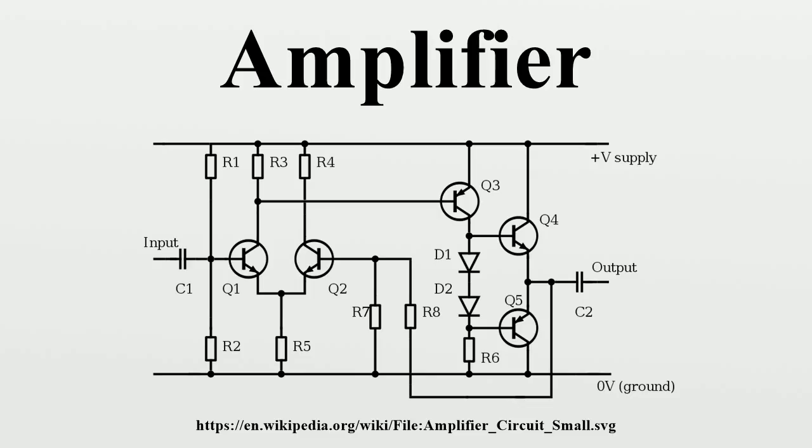Fully differential amplifiers. A fully differential amplifier is a solid-state integrated circuit amplifier that uses external feedback to control its transfer function or gain. It is similar to the operational amplifier, but also has differential output pins. These are usually constructed using BJTs or FETs.